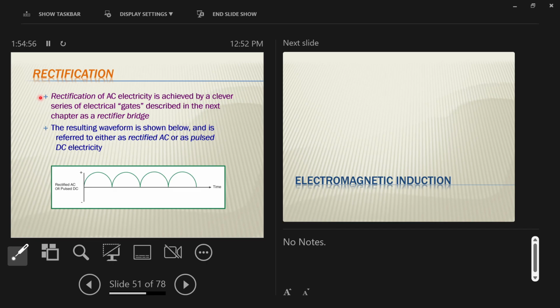So this is twice as efficient as half wave rectification. Notice this, you're making something happen the whole time. There is no space where nothing is happening, right? You have a pulse, followed by a pulse, followed by a pulse. You have acceleration, deceleration, acceleration, deceleration, but it's all moving in one direction. So it's effectively like DC current. It's like a DC waveform to the equipment. Okay? It would be better if we had this nice blocky DC waveform, but we get what we get, and the engineers that build this stuff have to make it work with our power that we access at the walls.